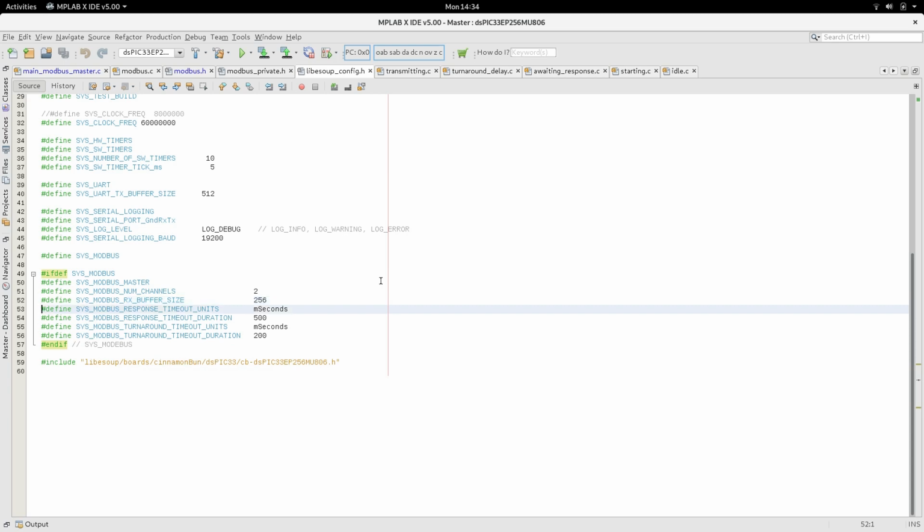So I must actually get rid of that as an option, as a switch. I suppose there is an advantage to keeping it there if you knew that, even though the MODBUS standard says it can transmit 256 bytes of a message, your implementation or your application only has one coil. In the case of our slave, we only know we're going to be sending one coil, 1 byte. Now that would include a number of bytes around that, but the maximum message size could be 5 bytes. So you could probably strip that down, and maybe there's a good reason for having that defined there.